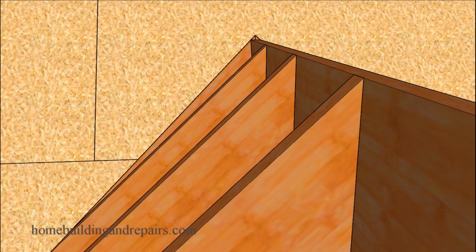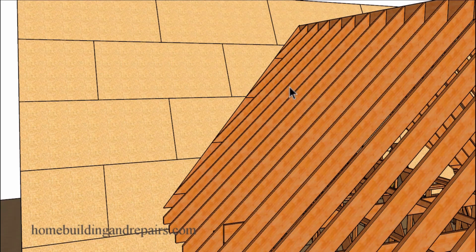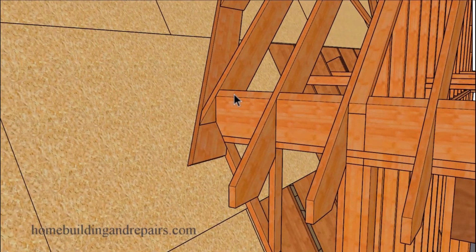That wouldn't be too difficult to do with a 45-degree angle. And of course, how the rafters will blend in, create a flat surface through the fill area. And our blocks, we're going to shape the top of the blocks. Again, not difficult to do with a 45-degree angle. However, it would be difficult to do for steeper roof pitches than a 12 and 12.